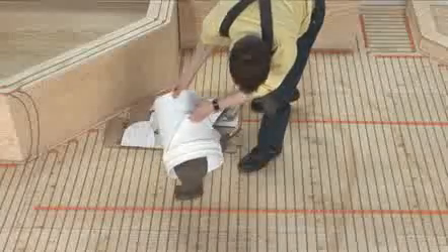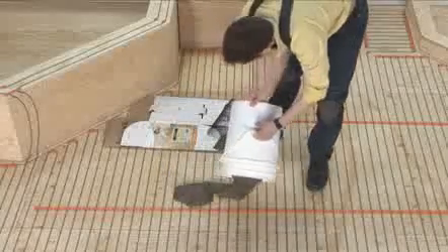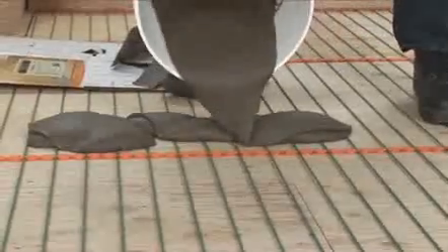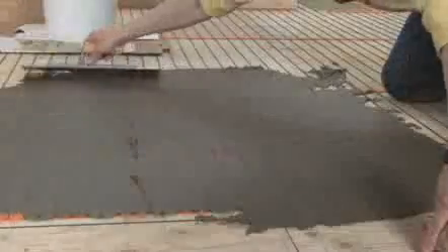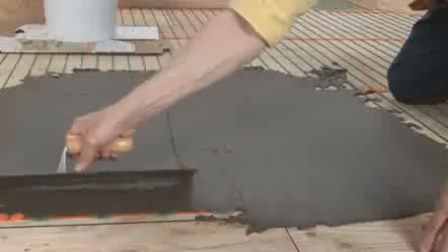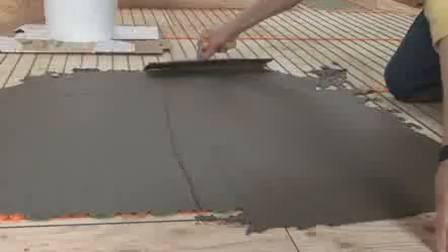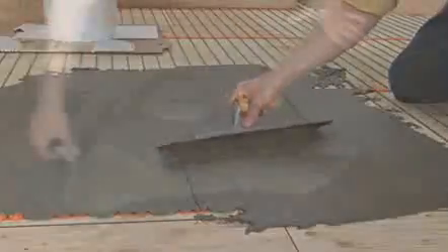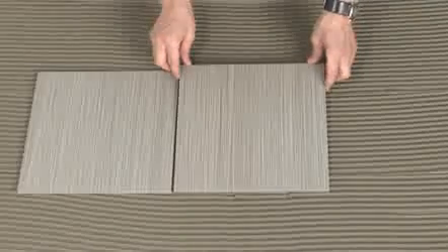The first technique for ceramic and stone uses glazing with polymer-based dry set mortar. Apply it in the same direction as the cables using a flat trowel at an angle of 45 degrees. When it is properly dried, usually after 24 hours, install the floor covering using the recommended adhesive. The glazing stabilizes the cable and facilitates installation of the floor covering.